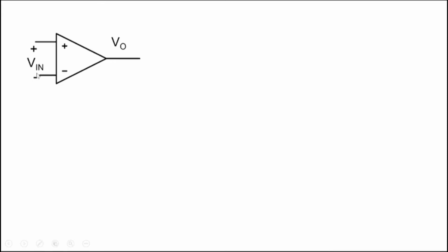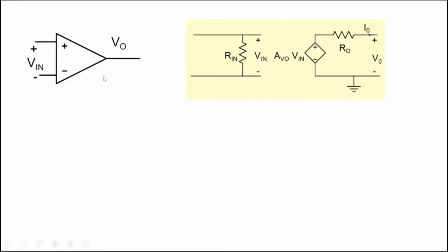All right, so let's look at this amplifier here. We are applying a voltage between these two terminals here, and we are taking an output here. Now the amplifier is complicated, right? Inside it, there may be several transistors, resistors, power supplies, all kinds of things. So what we are doing is determining an equivalent circuit model of the amplifier. Basically, if I look at it from the outside, external to the amplifier, how does this amplifier really behave? One way we can describe this amplifier is by this equivalent circuit here. If you look at the amplifier between these two nodes, whatever is inside the amplifier, we are not bothered, but the whole thing can be modeled. Now the word is important. It can be modeled as a resistor that you see here, Rin.